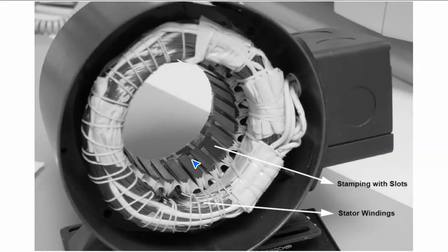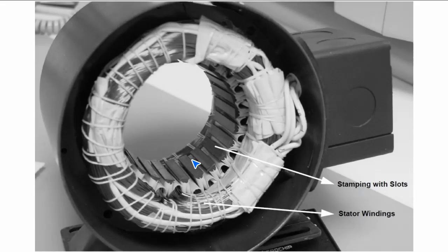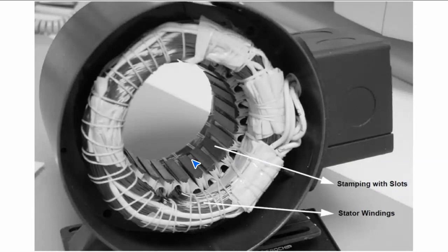Traditionally, the stator resembles that of an induction motor actually. However, the windings are distributed in a different manner. Most BLDC motors have three stator windings connected in a star fashion. What's the star fashion? Motors are connected as a star or delta. If all phases are connected at a single point, this is called a star or Y.